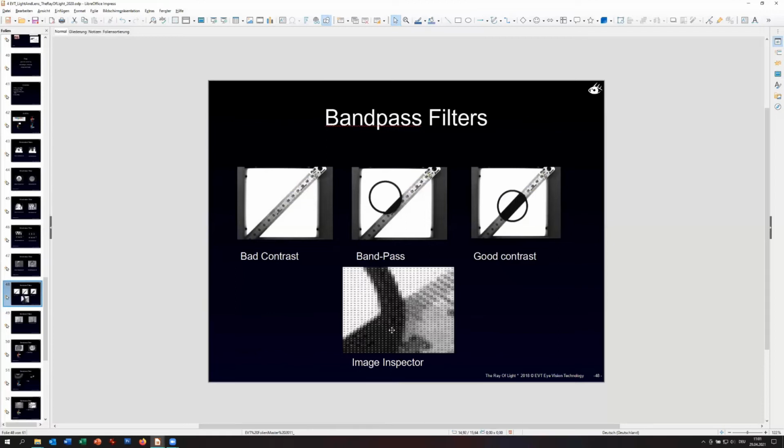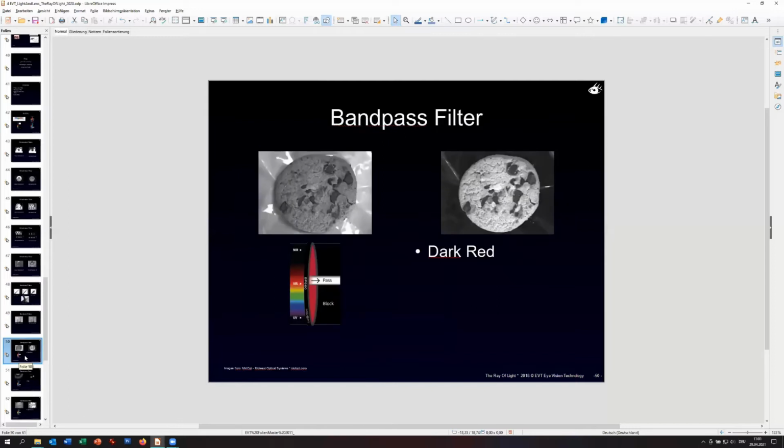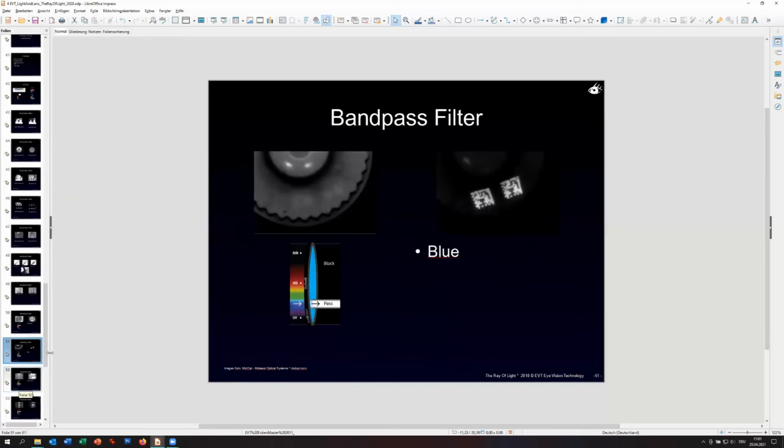And if you have to measure it in micrometers, you would say each pixel has, let's say, a micrometer or whatever, depending on the calibration. So it matters if you have a good light. This is what we really recommend before you start doing the evaluation with the software. Do the improvement either with the light or with a combination of light and filter and lens. In this case, it's no question. I think we don't see something, the camera doesn't see something.